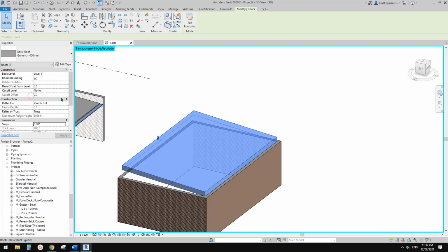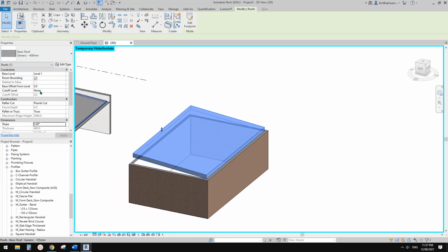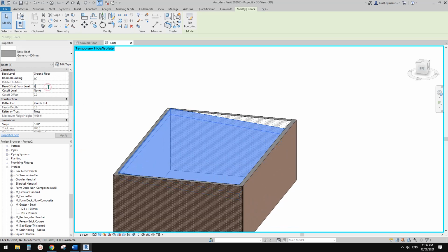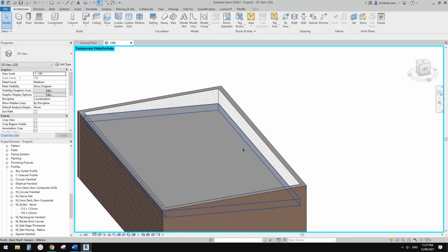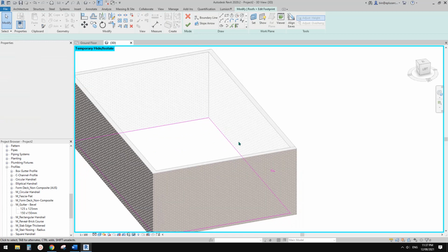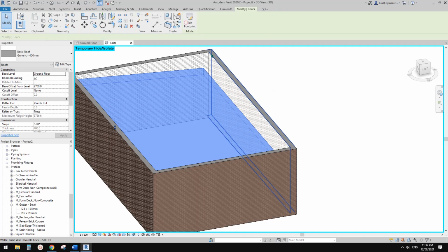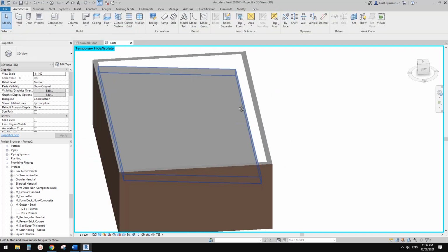Maybe let's just use this 401, and I'll change the height, ground floor 3 meters, for example, and yeah, maybe 27. Yeah, good. And then okay, so edit footprint and overhang. So for example, if I want to have a 300 box gutter, so okay, and then that's 300.